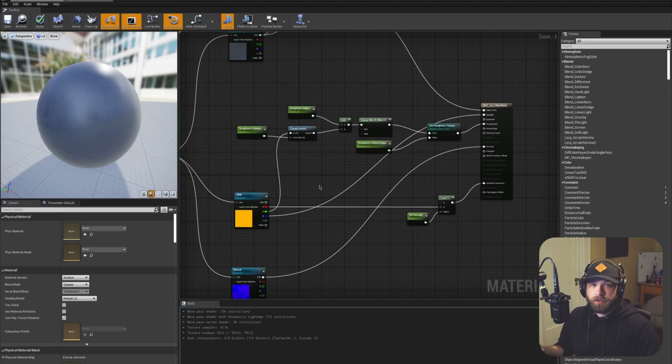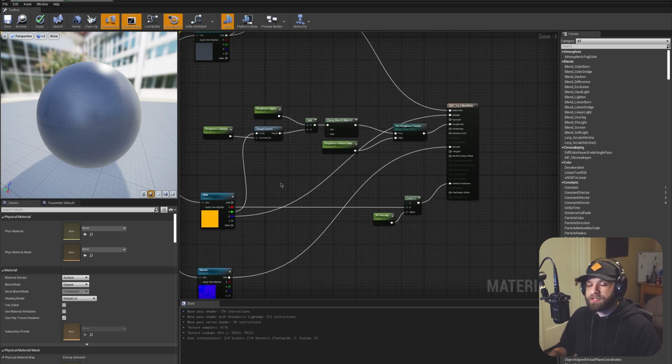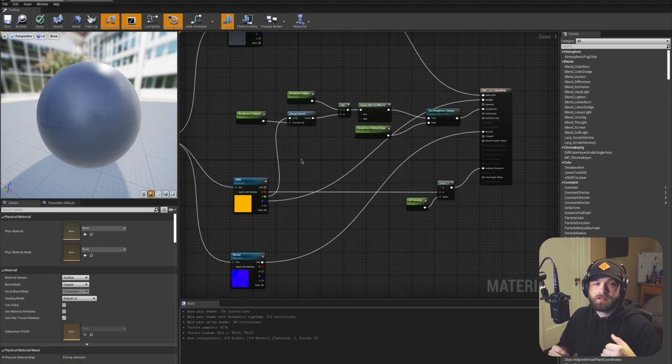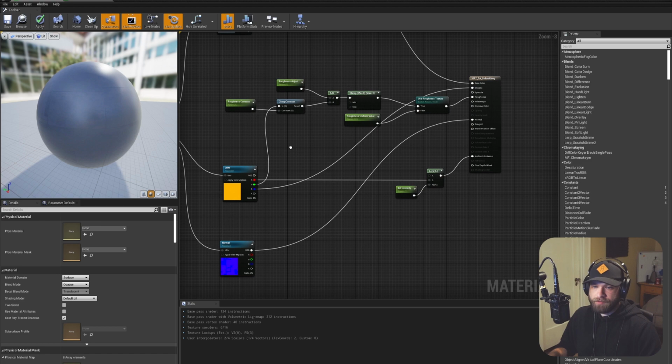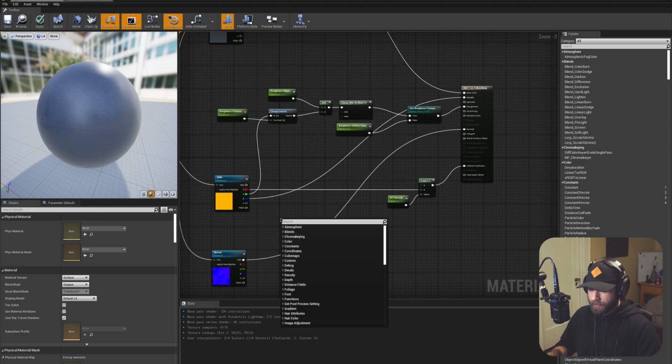So jumping back into the material here, we're actually going to do basically the same exact thing for the metalness channel. There's not any parameters that I can think of, for a basic master material, that would be necessary to have besides what we've already done here with our roughness, except specifically in the metalness channel. So we're going to go ahead and just repeat that process real quick.